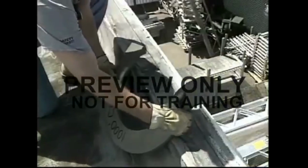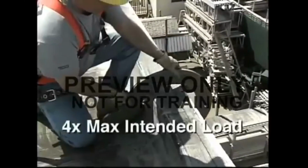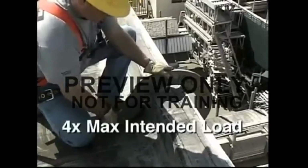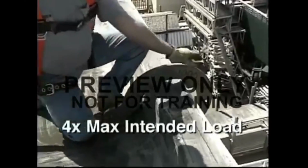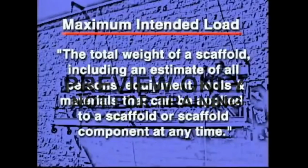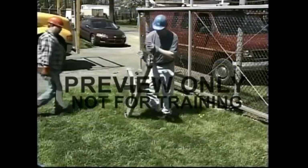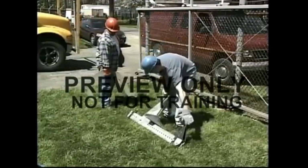These must be attached to parts of the structure that are strong enough to support 4 times the maximum intended load of the scaffold. OSHA defines the maximum intended load as the total weight of a scaffold, including an estimate of all persons, equipment, tools, and materials that can be applied to a scaffold or scaffold component at any time. All suspension devices must be made out of wrought iron, steel, or a material equal in strength to these metals.